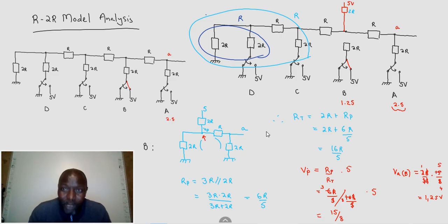So I don't know if you analyze this. We first resolved this. This was my first step. We got the R there. Okay. The second step is these R's become what? Since they're in series, they become 2R and they're now parallel to that. So this resolves to 2R parallel to 2R, which is another R. Alright.